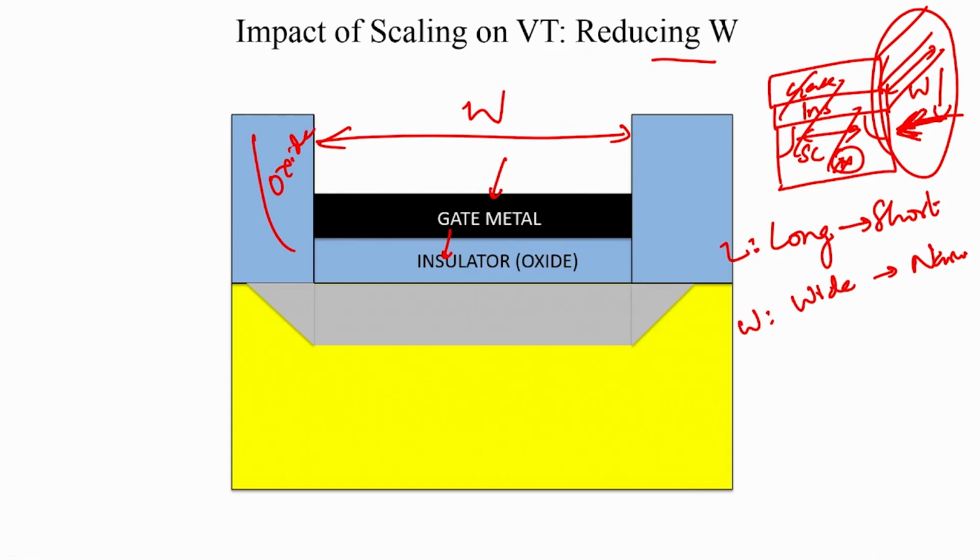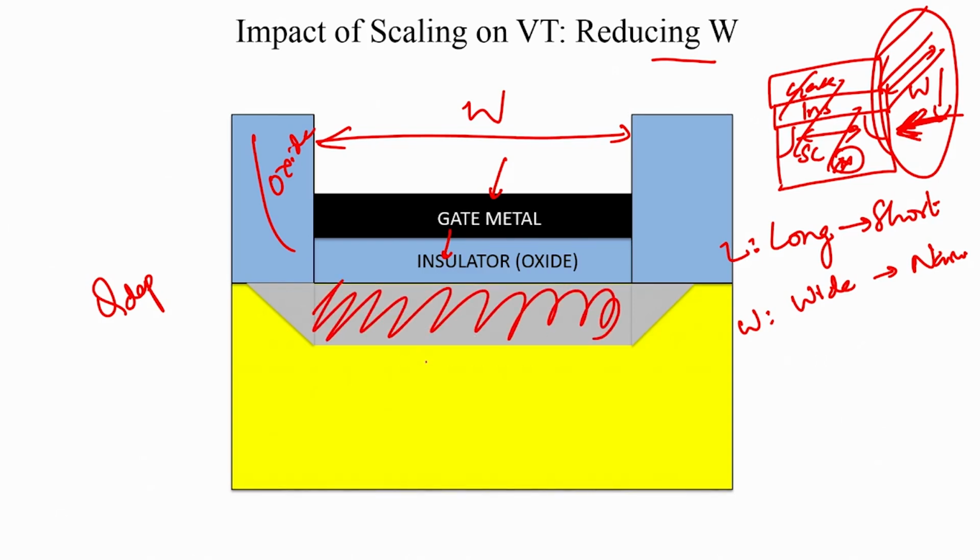Okay. So, let us look at the depletion profile. Once again the answer has got to do with the depletion charge, the total depletion charge. If you look at this depletion profile, yes, most of this depletion charge spans over a length of W, and of course, the channel length is say L, and therefore, W into L is what is depleted.